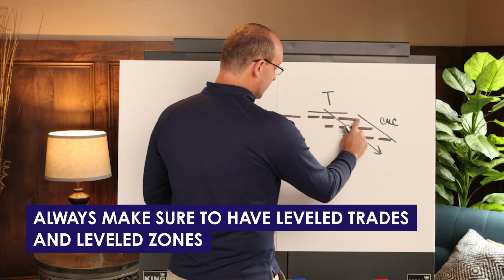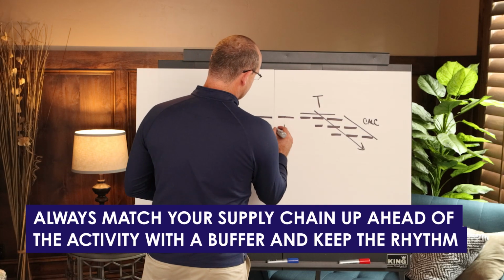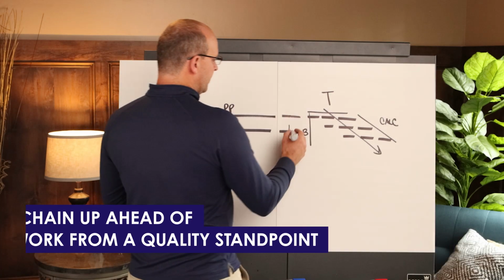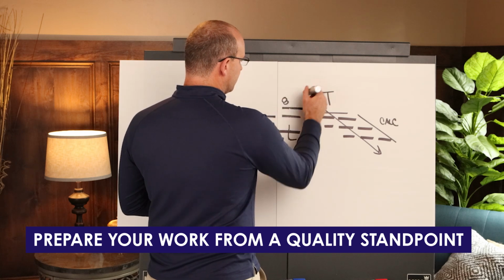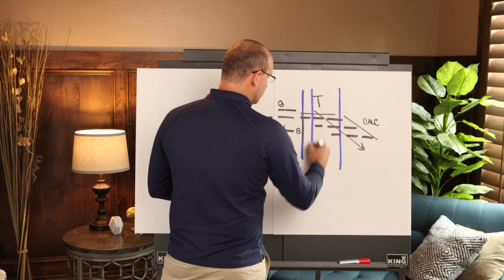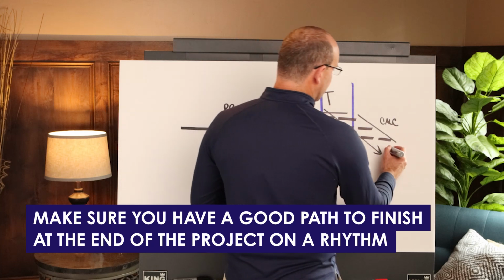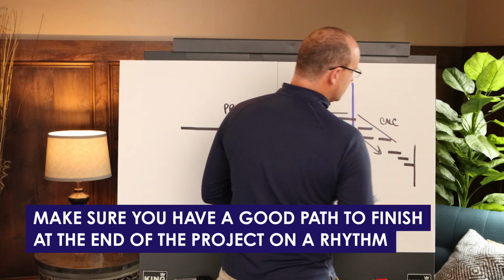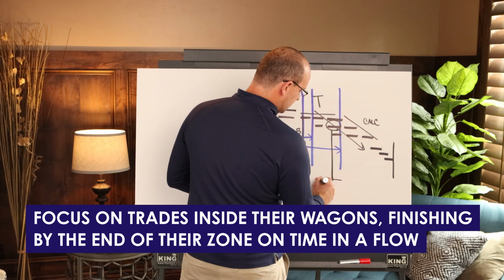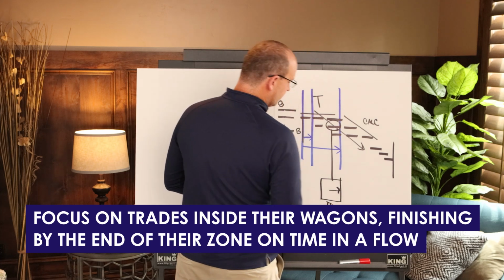And I want you to make sure you have leveled trades and leveled zones. I would really, really like you to match your supply chain up ahead of this activity with a buffer and keep that rhythm. Prepare your work, especially from a quality standpoint. And when you're doing your 6-week make ready, look ahead plan in your weekly work plan, make work ready and look for roadblocks. Make sure you have a good path to finish at the end of the project on a rhythm, and focus on trades inside their wagons, finishing inside their zone by the end of their zone on time in a flow. That's what you need to do.